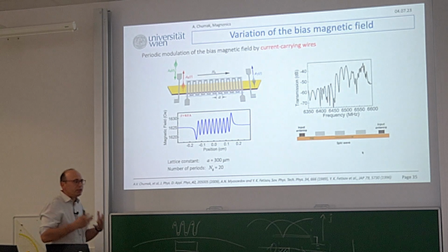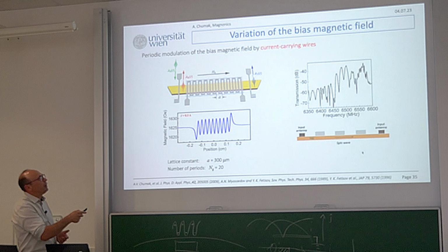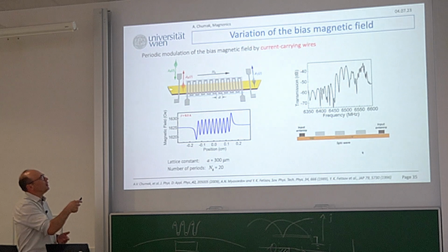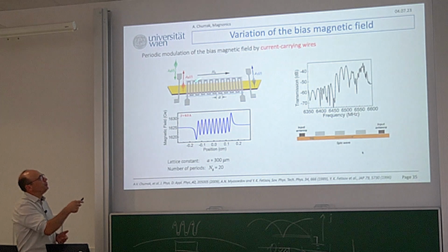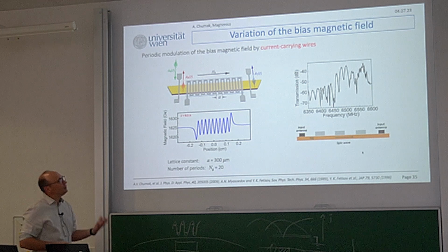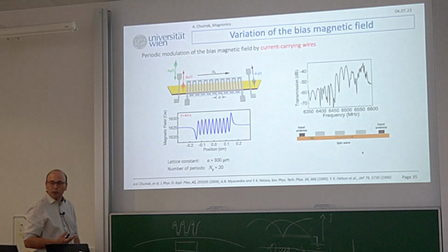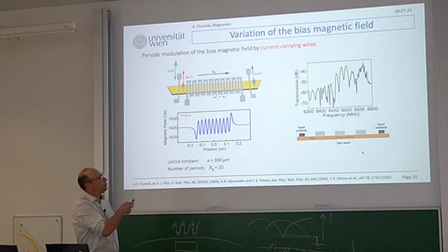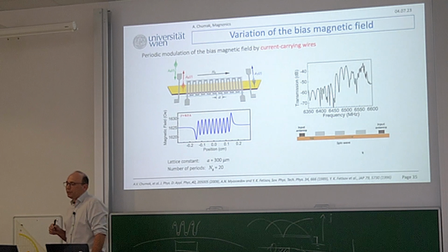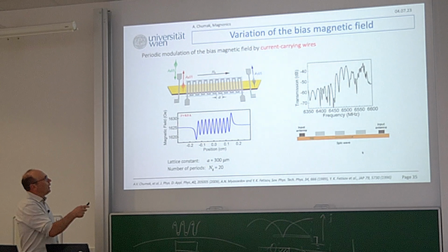And such a crystal is one where you change properties faster than the lifetime and faster than propagation. So this is your input antenna, output antenna. And you can change the media, switch on or off this magnonic crystal, like it's shown here, faster than the spin wave runs through. This we named dynamic magnonic crystal. Yeah? So it's opposite to reconfigurable. Reconfigurable means that you can change properties slowly. Dynamic means that you need to change it very fast, and then you will get access to new physics.